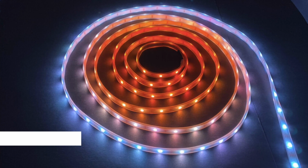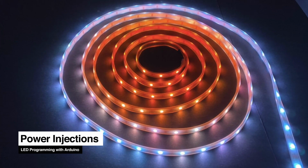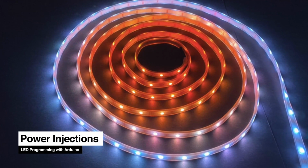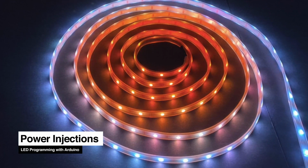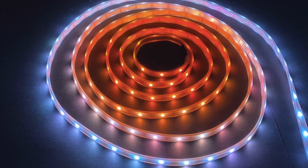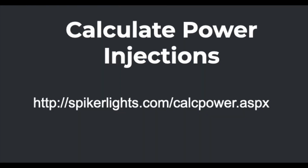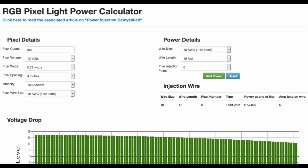We talked earlier about brownouts, which might happen if you aren't giving your LEDs enough power. To solve this problem, we can use power injections. As a rule of thumb, it's usually safe to add a power injection after every 50 5-volt red, green, blue pixels. This means you can power about 100 RGB pixels with a power injection on both sides without cutting the strip. You can use this calculator to help you figure out where to add power injections. Enter the values for your LEDs from the datasheet for your product.